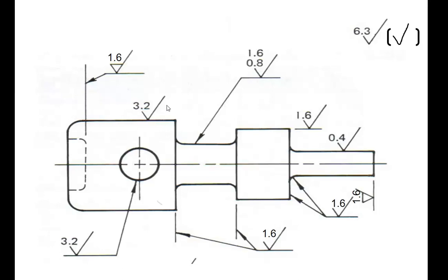If the region is crowded with some other annotations or dimensions, then use a leader line to reach a more suitable empty space in the vicinity.